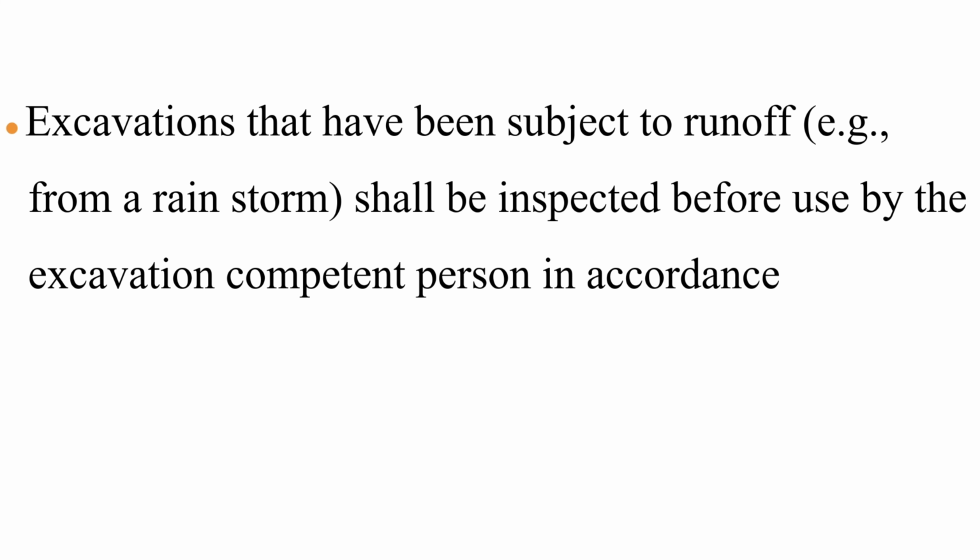Excavations that have been subject to runoff, for example, from a rainstorm, shall be inspected before use by the excavation competent person in accordance.